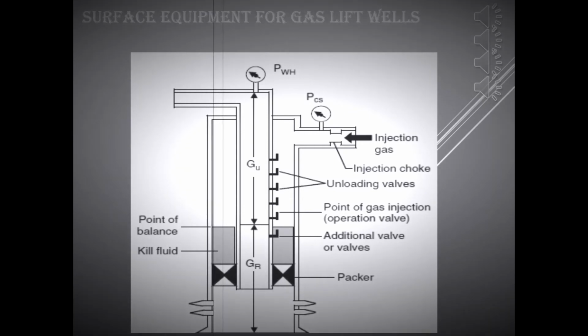For intermittent lift, it is a usual practice to install a time cycle controller. This controller periodically opens and closes by itself with the preset time and so periodically injects gas into the tubing. So, a time cycle controller has two basic functions. One is idle period of the cycle or time between two injection cycles like 15 minutes, 20 minutes, 30 minutes,